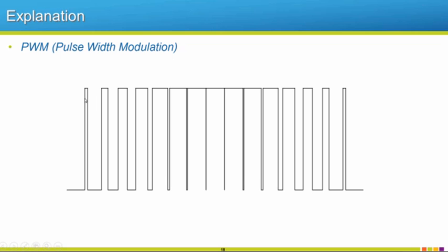But with the IGBT, we're able to vary how long we stay on. So if we're trying to form this sinusoidal output, we're not going to stay on very long at the beginning. So for this full cycle that's available, or this full period that's available for this IGBT to stay on, we're only staying on a very small amount of time. Then as we start to build our sinusoidal waveform, we start to stay on more and more, okay? Until towards the middle, we kind of saturate and we stay on the whole time, and then same thing happens with the other side. We start staying on less and less until we reach that 0 point, and then the other set of IGBTs start firing.